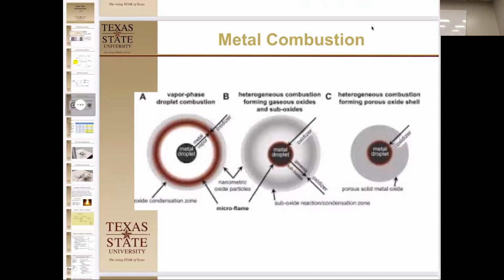But if it actually slides out, meaning it actually burns slow enough to create a hard coat, it actually stops and leaves some of the unburned silicon. Then there's the last one right here, which is something like tungsten, molybdenum, some of the heavier metals. What happens is the oxide and the metal doesn't even melt because it's not in the high melting temperature. It might melt, but it barely melts. The oxide has such a high temperature that you have to just slowly have it burn through the oxide, permeate oxygen through the oxide to burn.